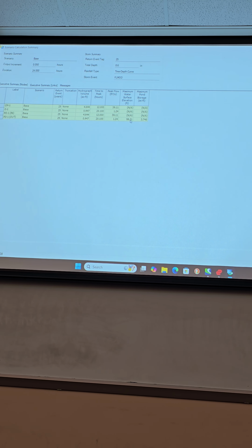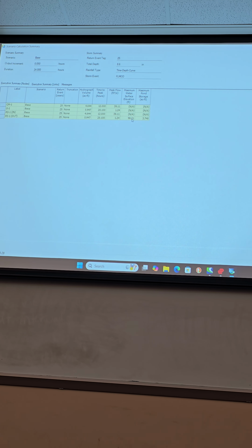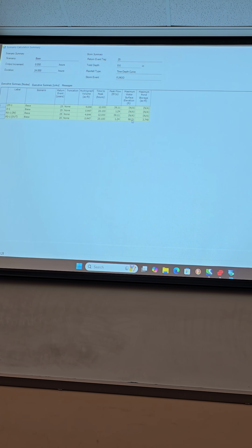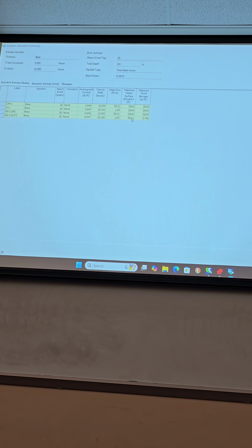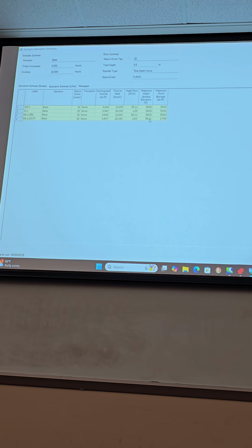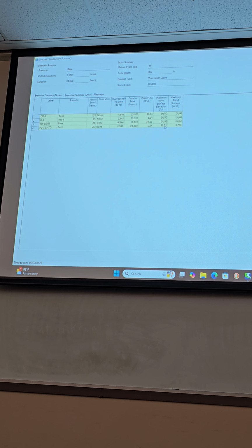That means you've overstated your basin in some way. Something went awry. You saw this for 10 acres, a curve number of 70 or 80, and a time of concentration of 20 or 30 minutes. The flow is 39 CFS. So that gives you some order of magnitude.